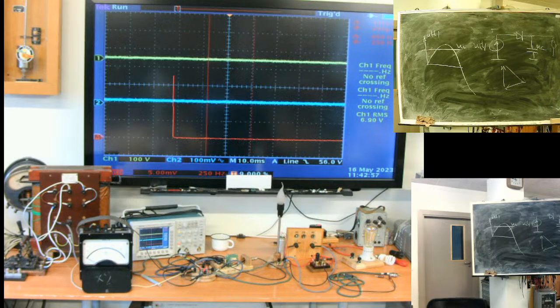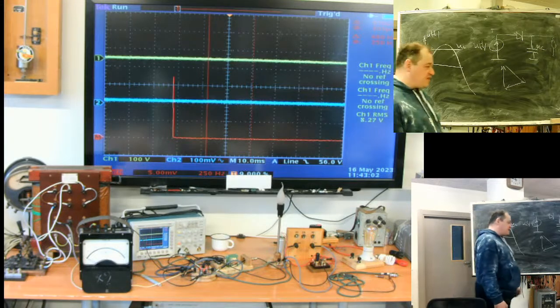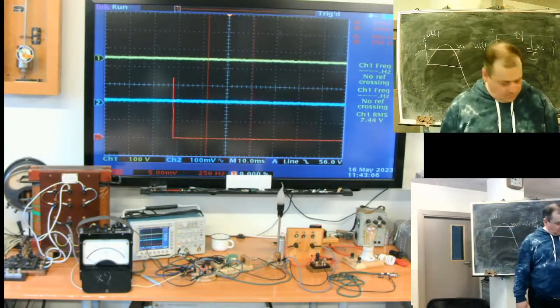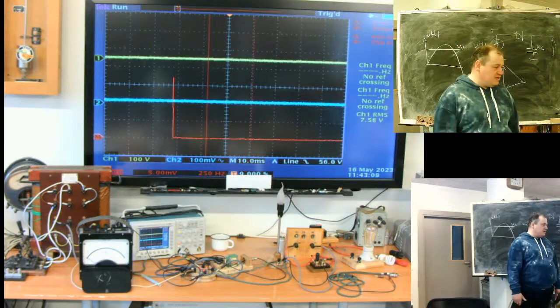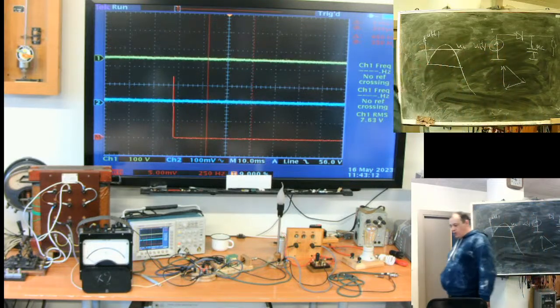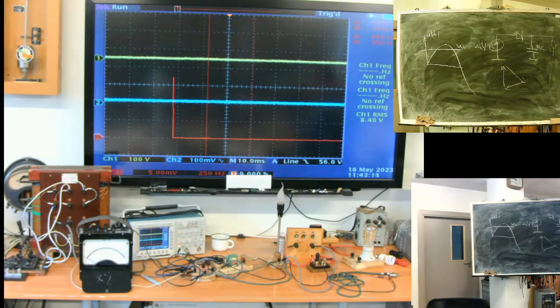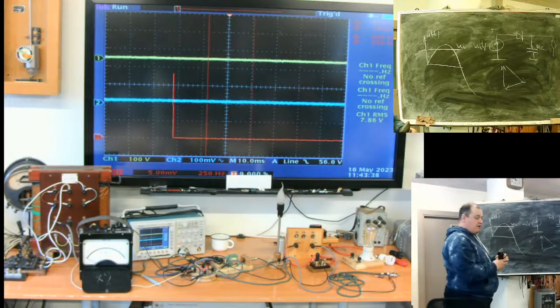I guess there will be some losses. No, not losses. 25 years ago it should be 0. Now, never. You have a building full of PCs, lighting and so on. You will see 5, 7, something like this. And if you ask why, and the guy answers it's a third harmonic, grab him. Grab him. If he answers something else, shower.